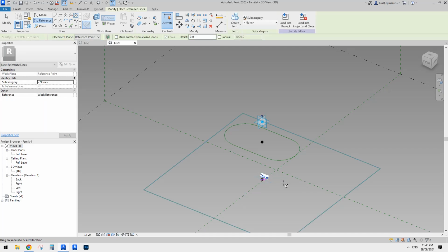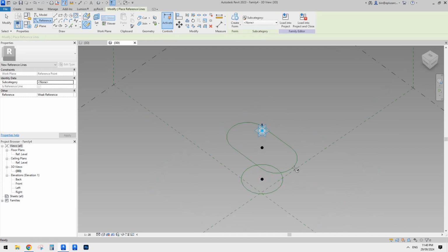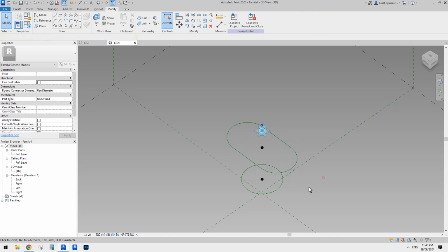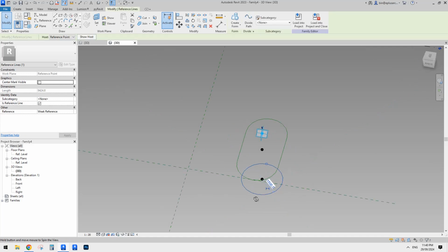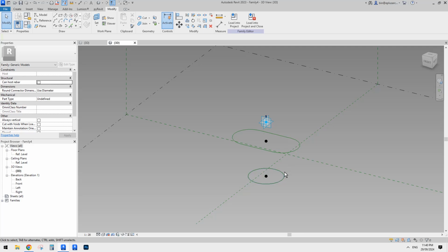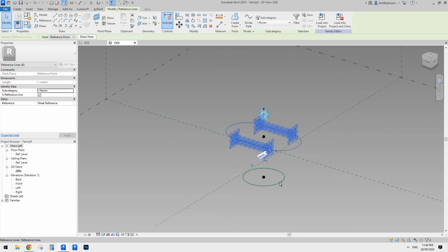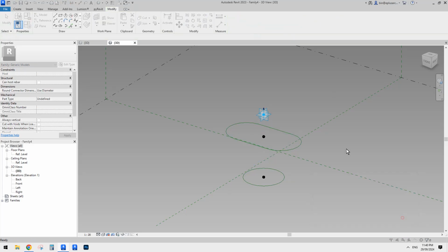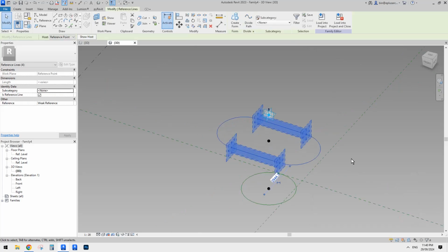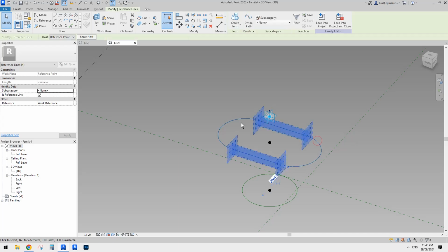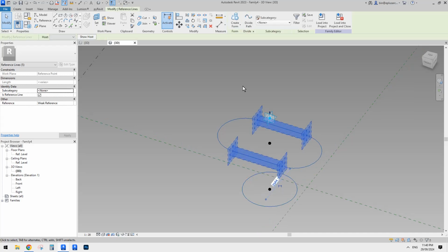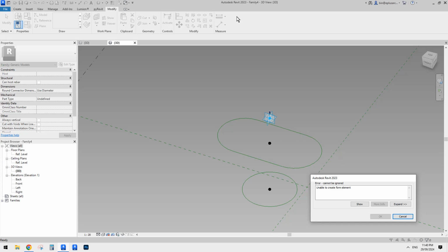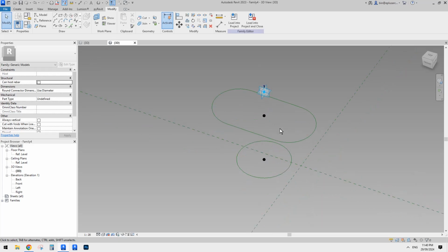and create. So I'm going to match this. For this one it's 1.5, so this one 1.5. Okay, now here we will have some issue. If we select these two profiles and create a form, no, Revit doesn't like it. Unable to create from element. Okay, that's fine.